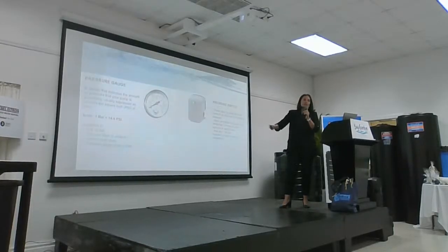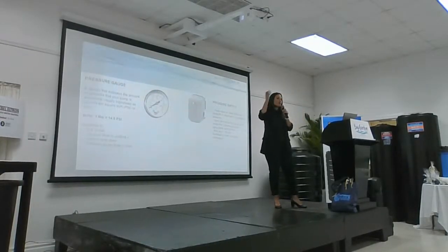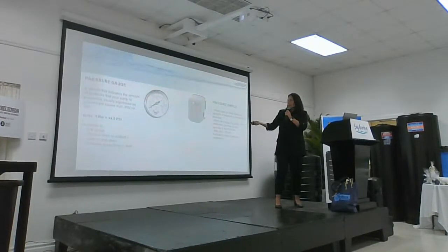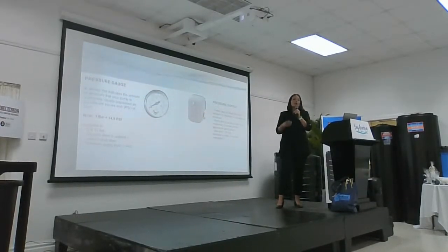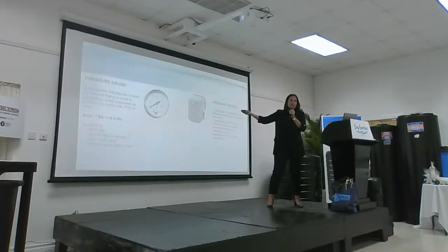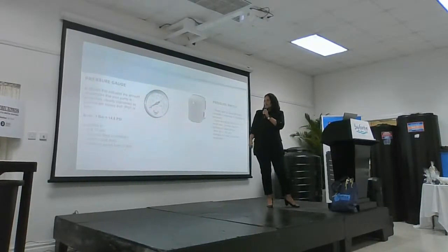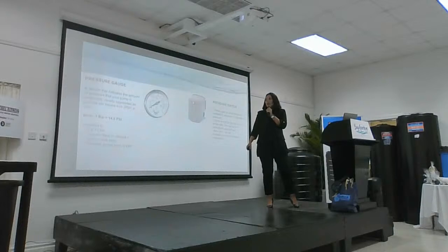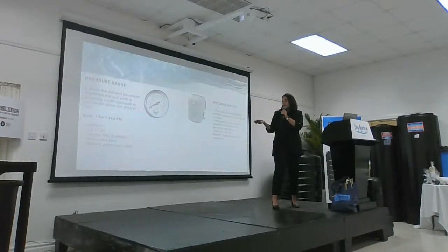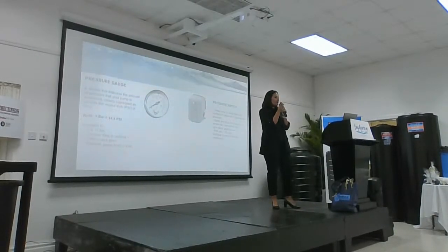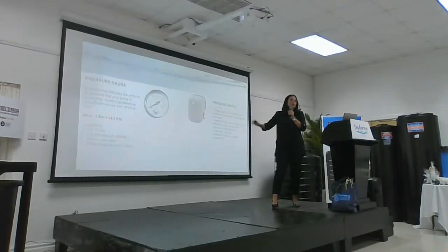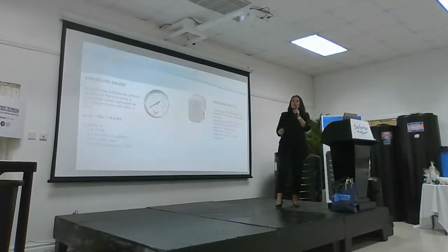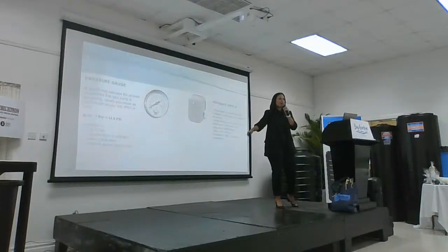With the pressure gauge, it will tell you the pressure that your pump is building. This is a clear indicator if something may be wrong with your pumping system, or if it's time for a maintenance check. We sell the pressure gauges separately, and they're available in 6 and 12 bar, in both glycerin-filled or unfilled. Then you can get the axial mount or the radial mount. Both come in 1/4-inch bore, made specifically for the Pentax pumps.